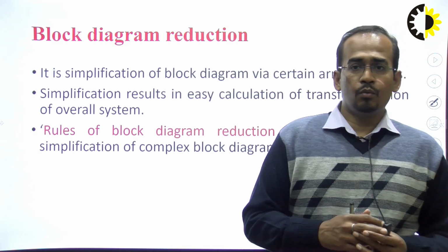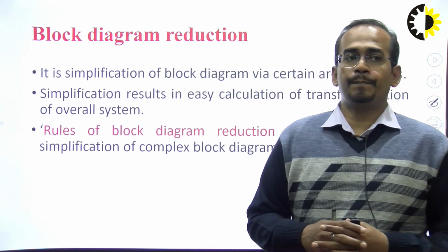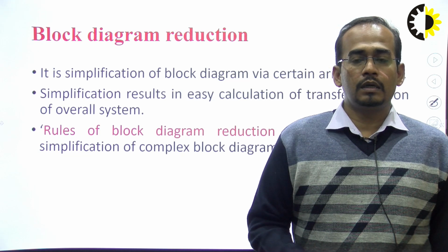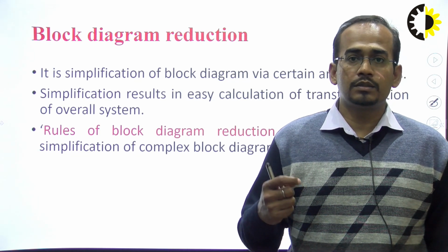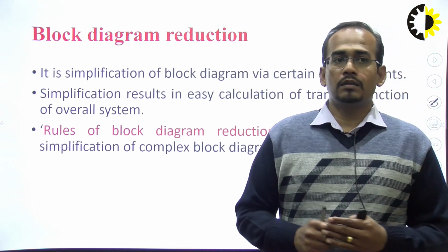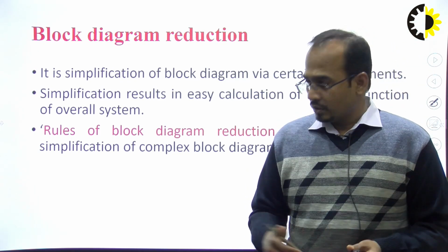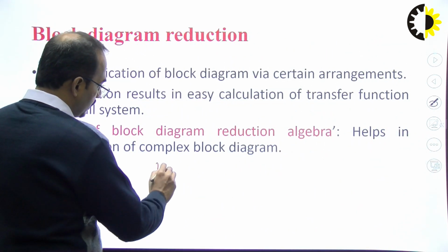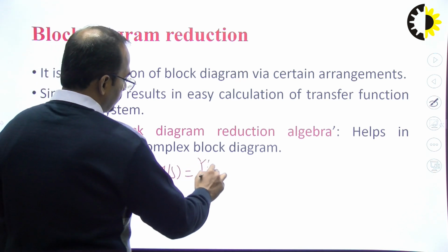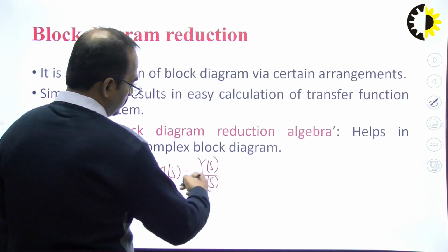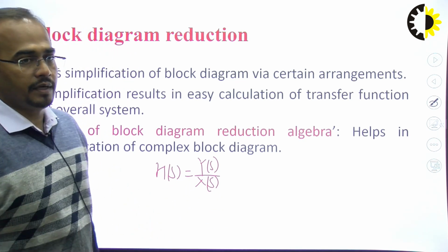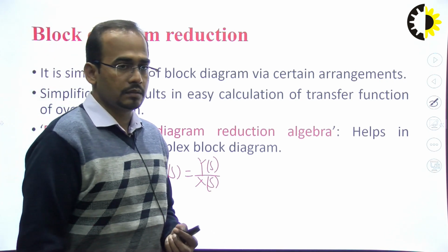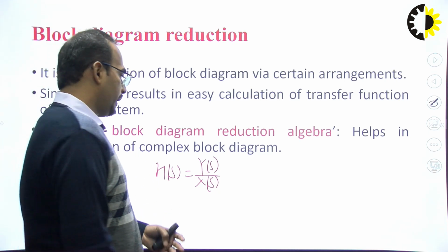And what is the transfer function? Transfer function is the ratio of the Laplace transform of output to the Laplace transform of input, considering all initial conditions 0, or considering the system is initially relaxed. Suppose H(s) is a transfer function, and you can define H(s) equal to Y(s) by X(s), where Y(s) is output and X(s) is input, or you can say Y(s) is the response and X(s) is the excitation.